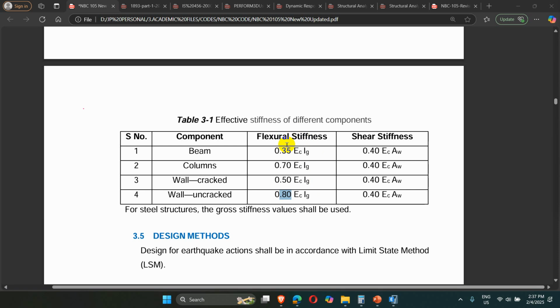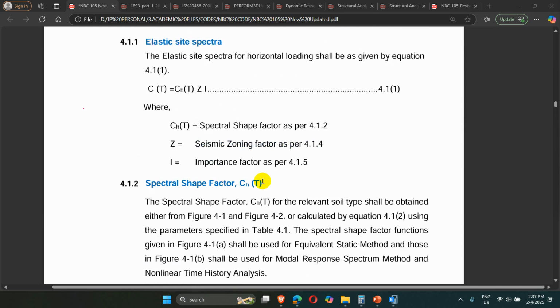And the low stiffness can cause the structure to deflect more with the given load, and it can be caused by using flexible materials, smaller section size, and insufficient cross-sectional area. Therefore, the less stiff structure will deflect more and experience higher deformation, leading to damage of the structure or failure, if the deflection exceeds the allowable limit. So different codes have different allowable limits for drift.